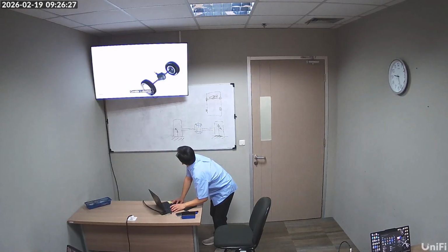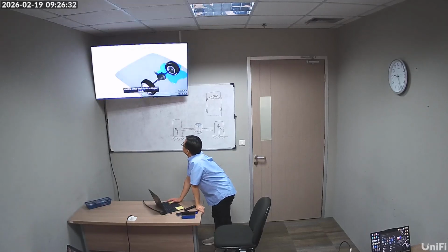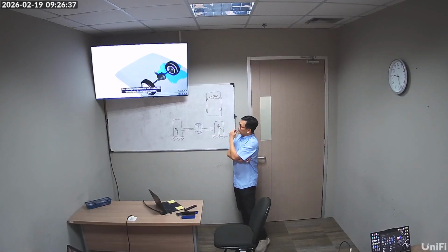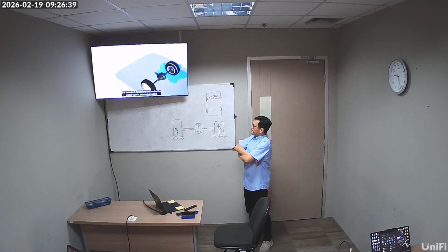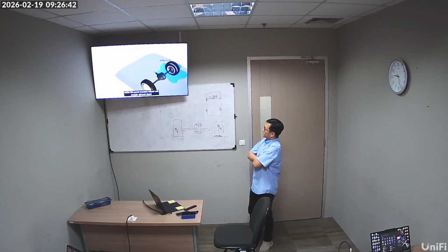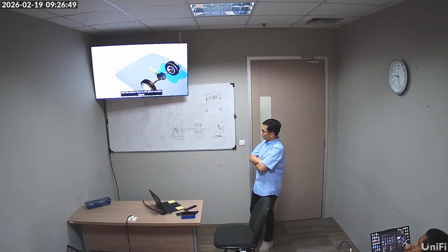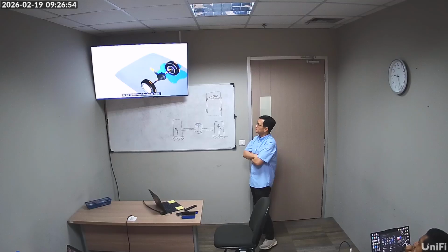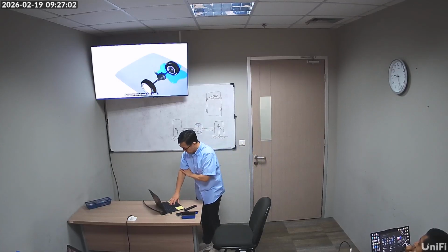Consider a situation where a vehicle fitted with the standard differential moves straight, and the drive wheels are completely independent. Since one wheel is on a slippery track, the standard differential will make that wheel spin at excessive speed, while the good traction wheel will remain almost dead. This means high power supply to the slippery wheel and low power flow to the good traction wheel. So the vehicle won't be able to move. One way to overcome this problem is to limit the independency or relative motion between the left and right axles.